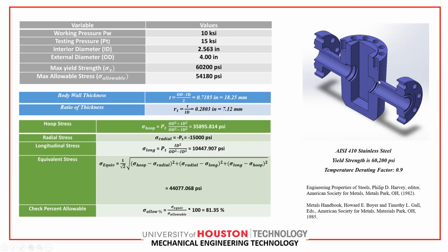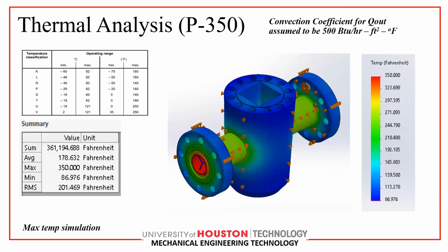So this picture is a half section view of the valve body. And so we know also the temperature rating factor, as I said, is equal to 0.9. This slide is about the thermal analysis, testing with the maximum temperature. We know our design criteria, the temperature class is 350 Fahrenheit degrees, which is the maximum temperature.